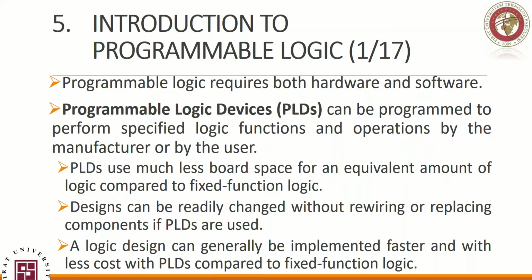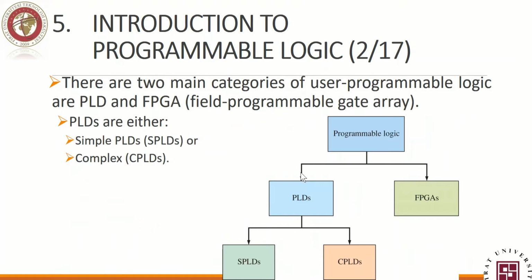So if you are designing a one-time machine or one-time application or one-time device, you can use fixed function logic if it is cheaper, if it fits your own need. If you're going for something reprogrammable or something that you may program in future, you may think about PLDs or the complex version of PLDs. Okay, so let's first discuss programmable logic, then we will go to fixed function logic.